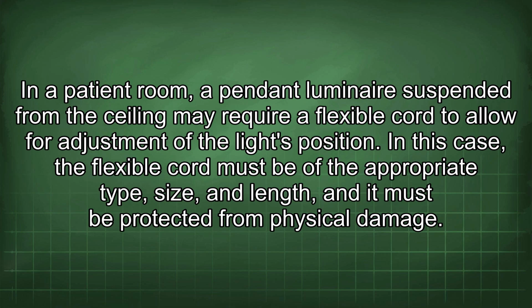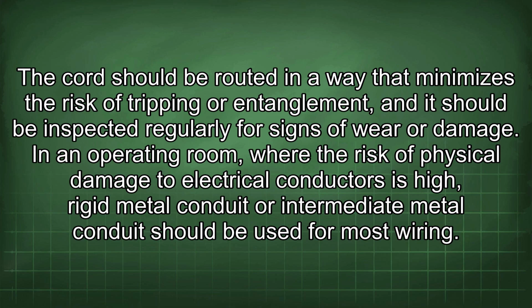In this case, the flexible cord must be of the appropriate type, size, and length, and it must be protected from physical damage. The cord should be routed in a way that minimizes the risk of tripping or entanglement, and it should be inspected regularly for signs of wear or damage.